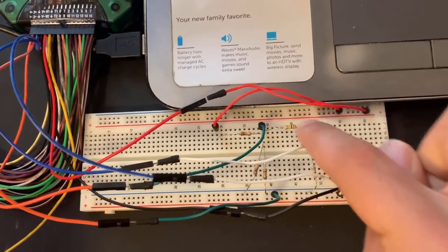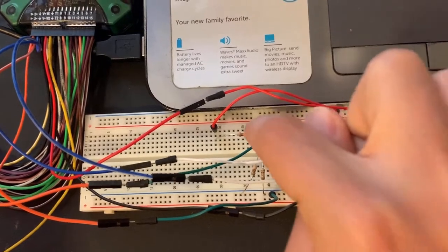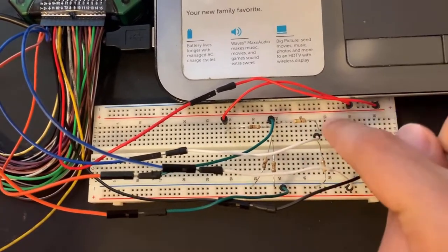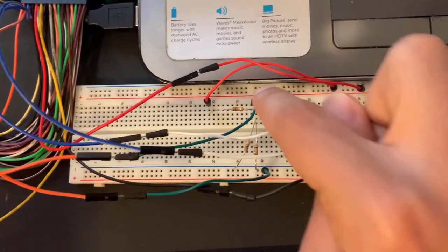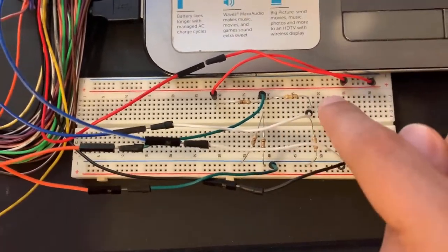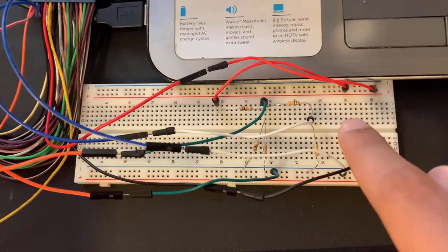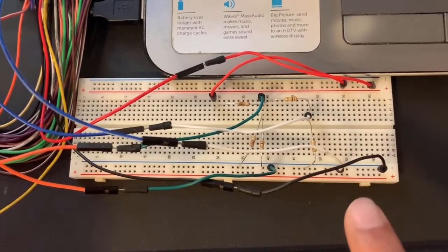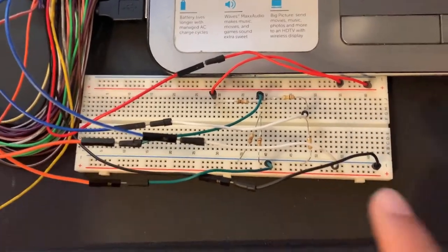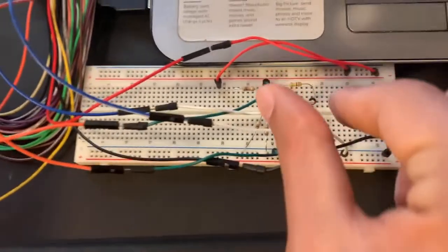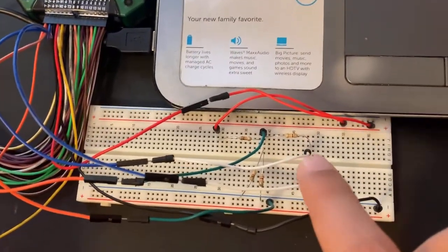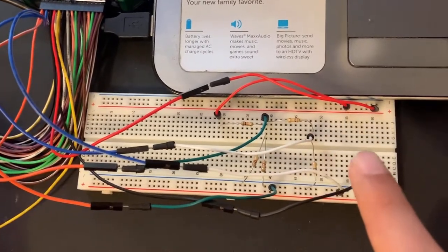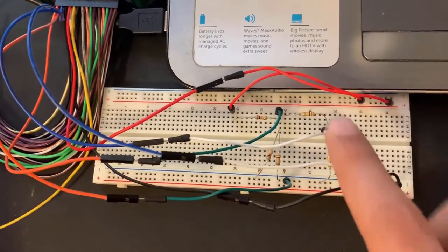For R4, the drop is equal to V1 minus V2, okay? V1 minus V2 times the current flowing through this resistance, which is equal to I3. So it will be equal to 0.416 minus 0.191, the difference in voltage, times the current I3, which is 0.00191, which is equal to 0.443 microwatts.